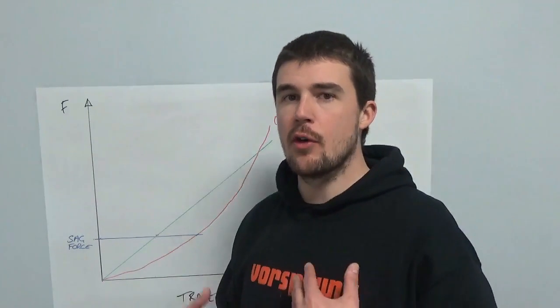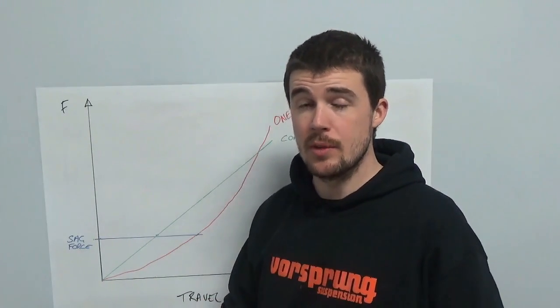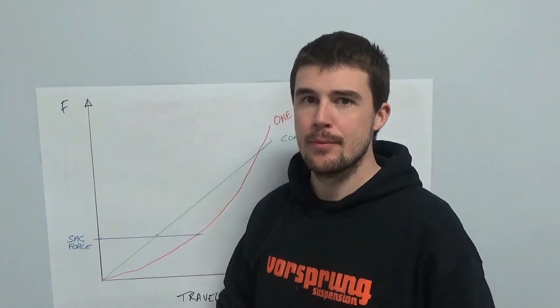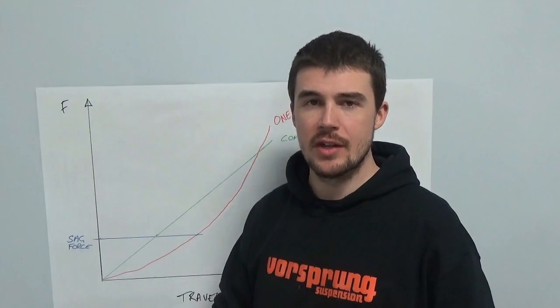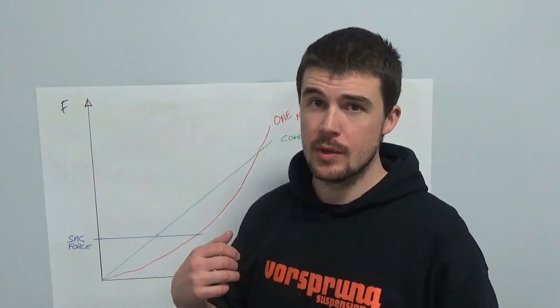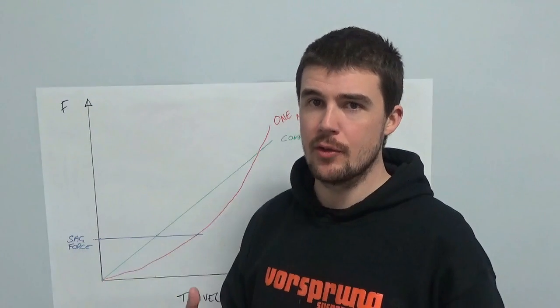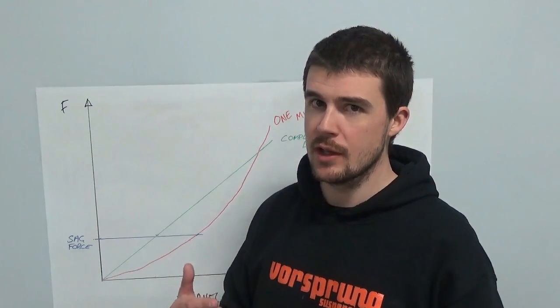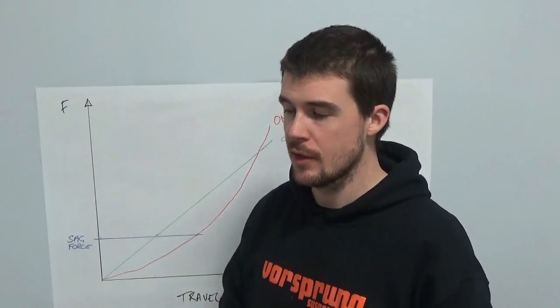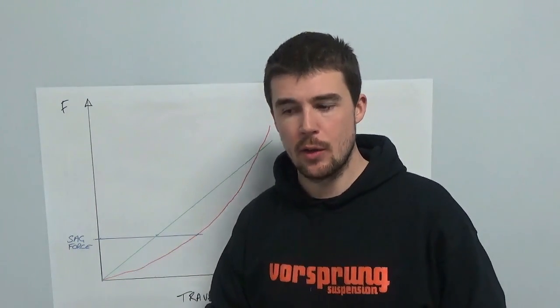However, if that's overridden by the perception of it being too deep in the travel, that's what we need to really ascertain and work out. Do you want something that has a higher force in the middle of the travel? Do you want something that has a higher stiffness in the middle of the travel? They're not necessarily the same thing. Stiffness being force divided by distance. So that's number one out of the way.